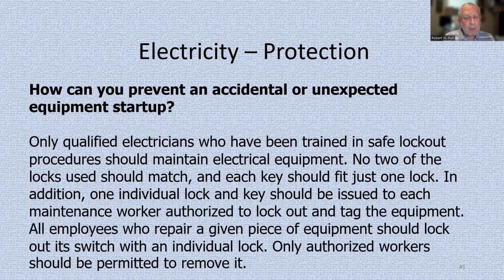Only qualified electricians who have been trained in safe lockout procedures should maintain electrical equipment. No two of the locks used should match, and each key should fit just one lock. In addition, one individual lock and key should be issued to each maintenance worker authorized to lock out and tag the equipment. All employees who repair a given piece of equipment should lock out its switch with an individual lock.